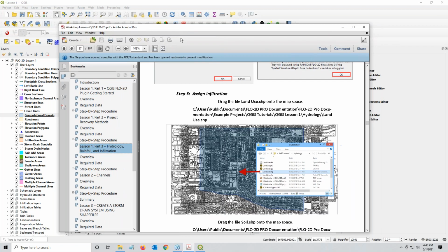So now we're going to move on to the infiltration data. Now the Flood Control District of Maricopa County uses Green-Ampt infiltration. Pima County uses SCS infiltration. I don't know what Mohave County uses, but I think they might also use Green-Ampt. And then every other county uses some kind of version of whatever. They might use some kind of version of either of those. So if you're doing a Maricopa County project, you're going to have some extensive good data to use. And this is the process you'll use for them. I will do another video on any other processes.